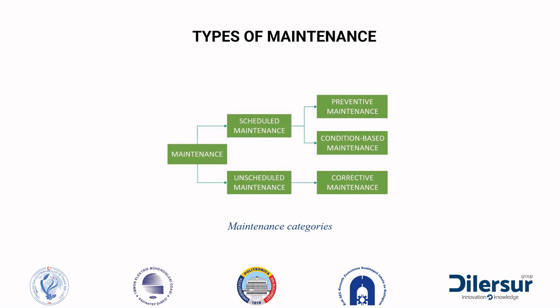This method uses periodic measurements to detect signs of equipment deterioration in order to extend its service life by avoiding imminent problems. It improves the performance and efficiency of solar systems by anticipating failures and avoiding them at an early stage. Condition-based maintenance requires special diagnostic equipment and a good equipment performance monitoring system, which can extend and improve the life of the solar plant.